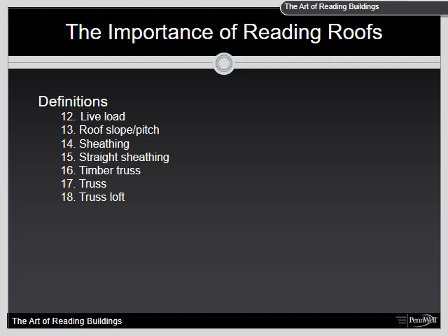Timber truss. These are large dimension lumbers used to form a truss. They are commonly found in older roofs. This type of construction is normally made from full dimension lumber and is often comprised of multiple members bolted together to form one structural member.